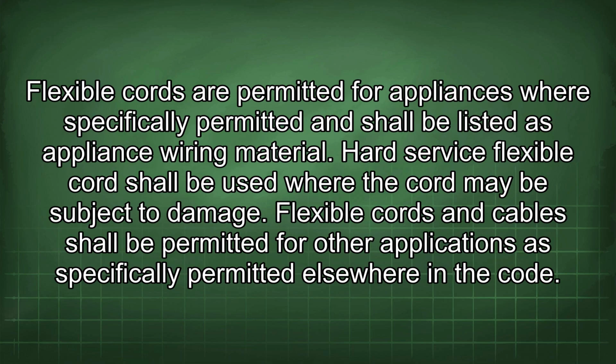Flexible cords are permitted for appliances where specifically permitted and shall be listed as appliance wiring material. Hard surface flexible cord shall be used where the cord may be subject to damage. Flexible cords and cable shall be permitted for other applications as specifically permitted elsewhere in the code.